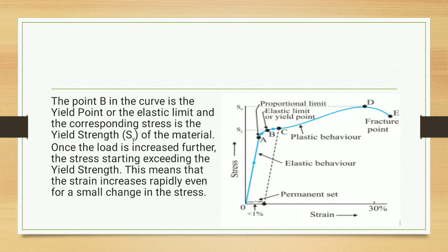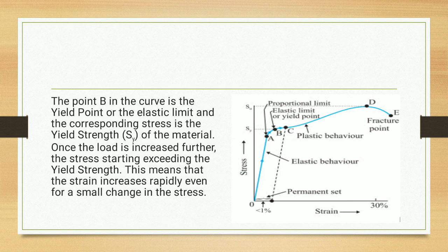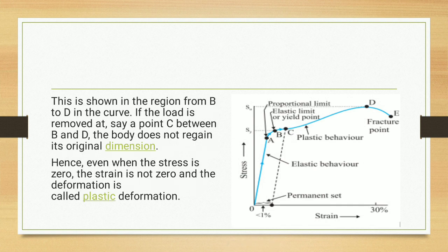Once the load is increased further, the stress starts exceeding the yield strength. This means that the strain increases rapidly even for a small change in the stress. This is shown in the region from B to D in the curve.